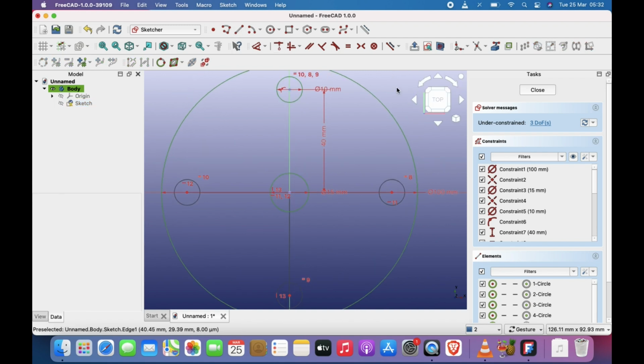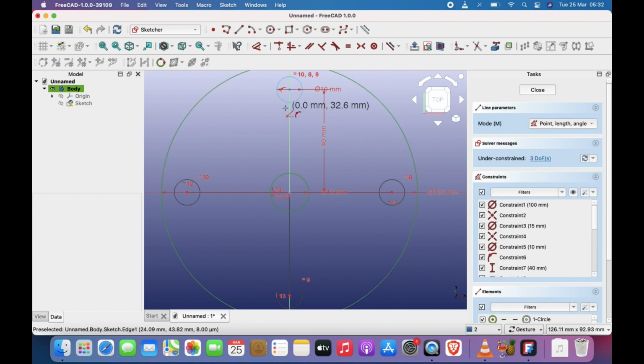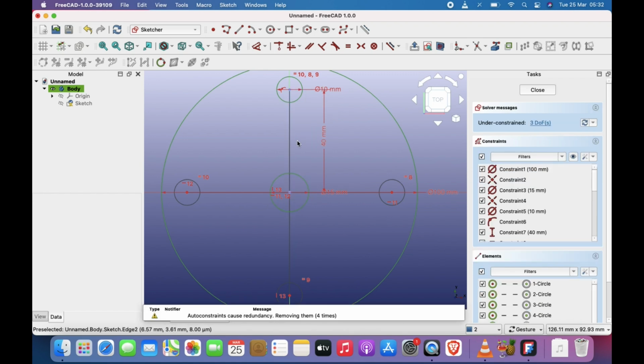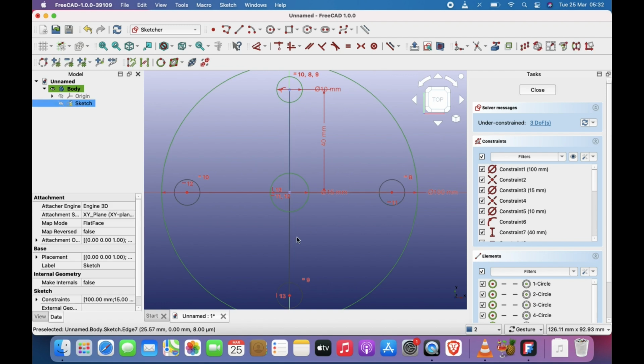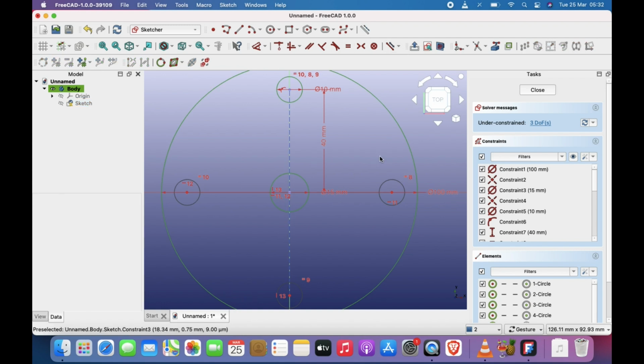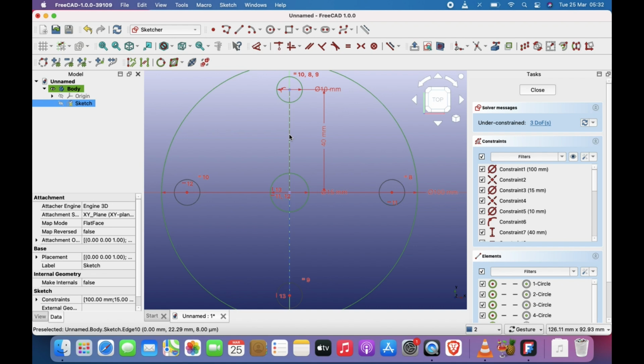And if you don't like this line way, just dimension it. That's simple. But I'm just showing you how to create parametric designs. So I'm going to click on that. So simply, I know that this line is already dimensioned to be 40, and I'm going to make all of them construction lines. So I'm going to select all of them, command or control, select, and I'm going to change it to construction lines. Then I'll select them again, select all of them.